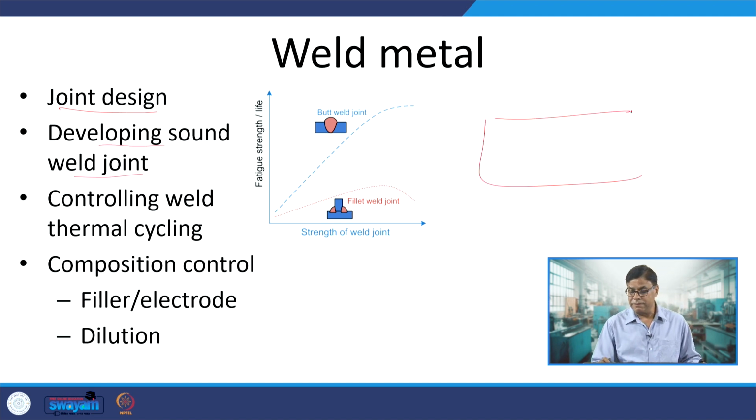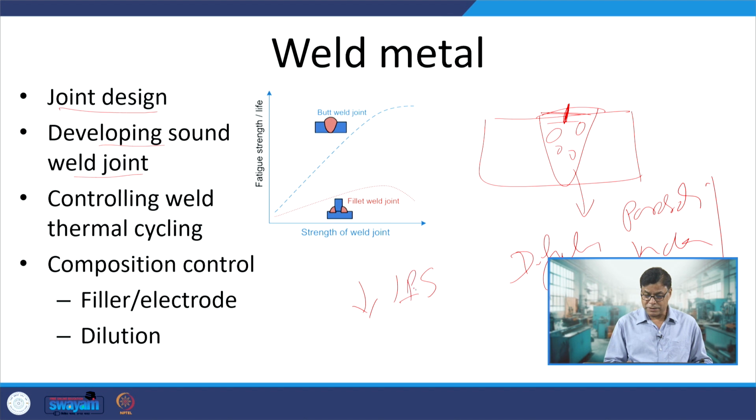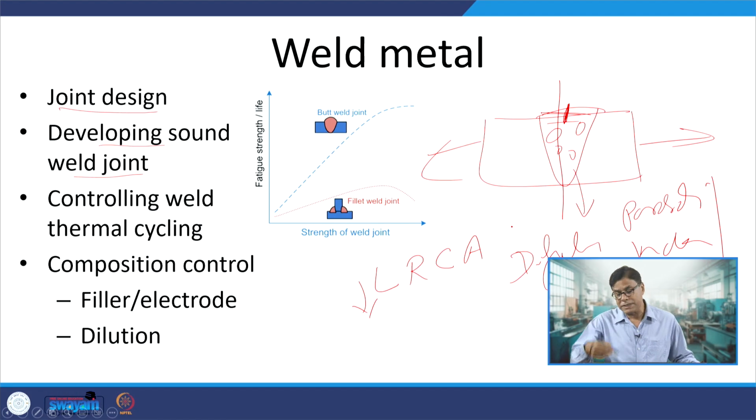As I have said, if the weld metal produced through fusion welding has either a crack at the center, or porosity, or inclusions, then these defects in the form of porosity, inclusions or cracks are going to act in two ways. First, they will be reducing the load resisting cross sectional area. So, this is one, when defects are present under tensile loading, they will be reducing the load resisting cross sectional area, and therefore, nominal stresses will also increase.